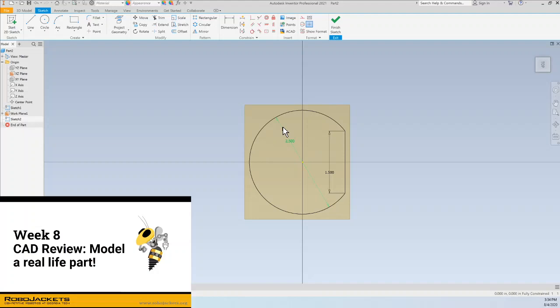And this shape is a little complex, but I'm going to do the best I can. So the straight edge is going to be 2 inches. So I'll just make a line over here. That's the correct angle. And it's 2 inches. And then I'm going to make sure it's the correct distance from the midpoint. So I'll make it parametric, so that if I ever want to go back and fix this measurement to something more specific, it's really easy. And once I change it, it'll always be halfway between.